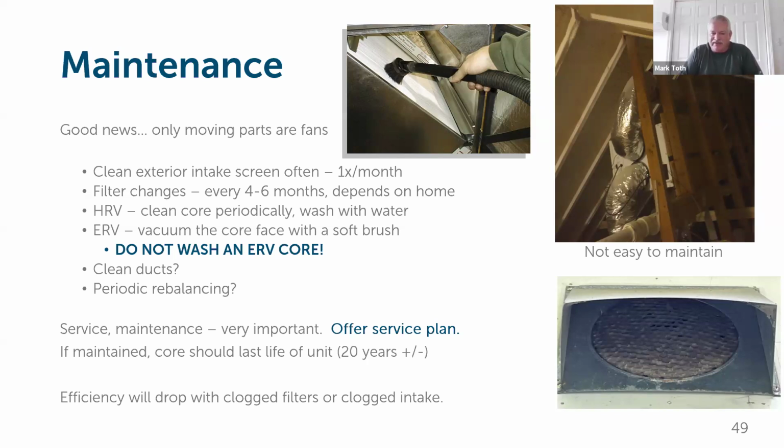Also, the outdoor vents, as we talked about, that's another one in that same house I showed you from earlier. Completely plugged. Most of that's tree pollen. That was in the spring. A lot of that is the white cottonwood, floating seeds in the spring, and it gets full of that. But also, again, they'll get full of leaves on the suction, grass clippings, bugs. They do need to be maintained.